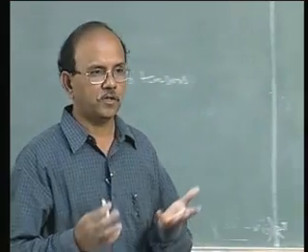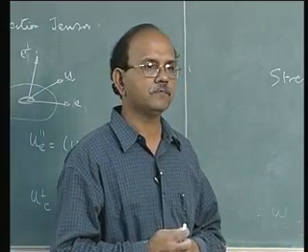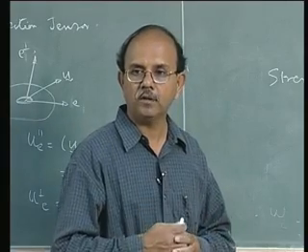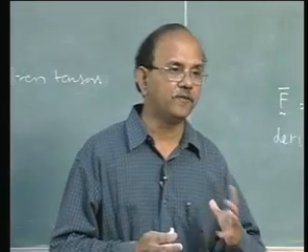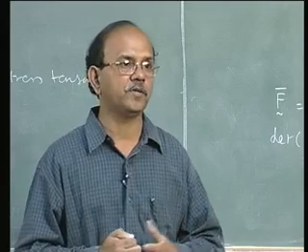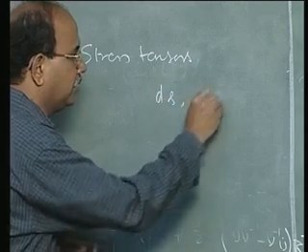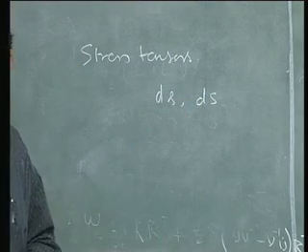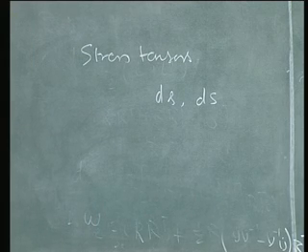All of us are familiar with the Cauchy stress, sigma. We had used that in the earlier course. We were not worried about change in the area and so on, because all of the deformations which we had considered till now are infinitesimal deformations. But now since we are looking at finite deformations, there is a change in area, and we had a formula which connects ds and capital DS, the original area, with small ds, the final deformed area.